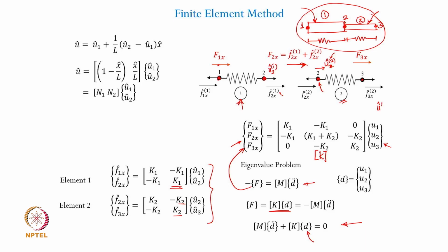You can assemble these matrices together and you can see that in this case this particular element in this global coordinate system is going to be lying here in this particular position, whereas this entire matrix, this element is coming back here and that matrix is appearing here. Okay. So this is how we assemble it. You can see that U1 is on the first row, U2 is representing the second and U3 is representing the third row, right. That is how they need to be appropriately assembled together.